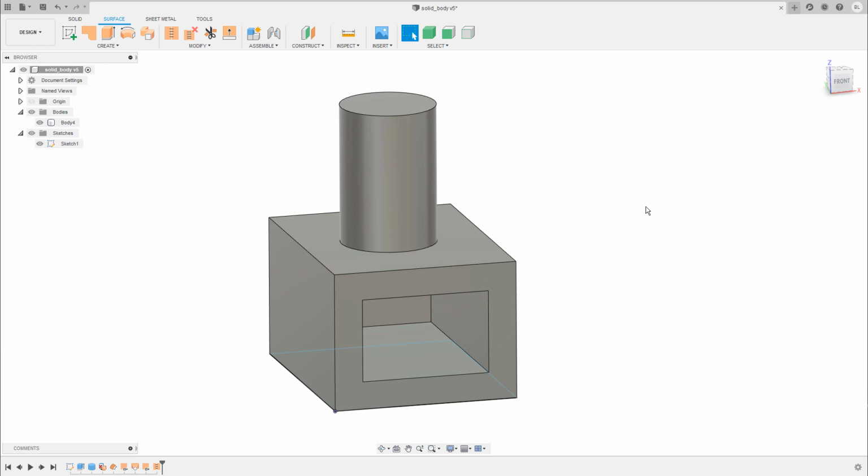You have to be careful with these operations because it depends on how well you have constructed the model. This starts with the initial sketch and also the features that you apply step by step. So it requires some experience to build models where you can scroll back in time, make large adjustments, and have the model updated when you move the slider over to the right again.